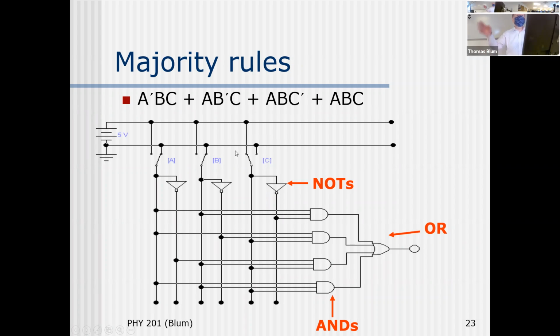It matters how it's connected. Sometimes these switches will be horizontally oriented, and high does not mean the switch is up. The switch high means that the switch is connected to a high voltage. It's always about the connections and the voltages, not what's physically higher on the page. That's irrelevant.